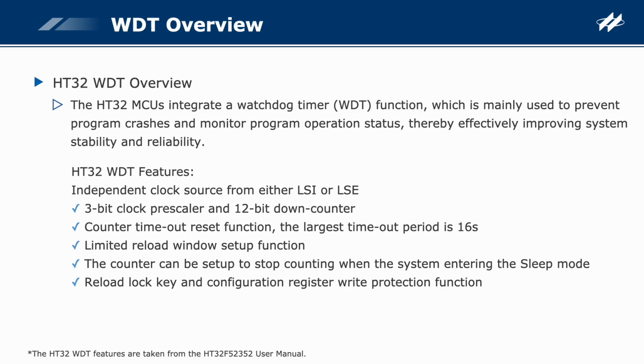The counter can be set up to stop counting when the system enters the sleep mode. The WDT provides reload lock and configuration register write protection functions. Note that the LSI clock source of the watchdog timer is subject to drift depending on the operating temperature and conditions. This results in the WDT timing not being absolutely accurate.